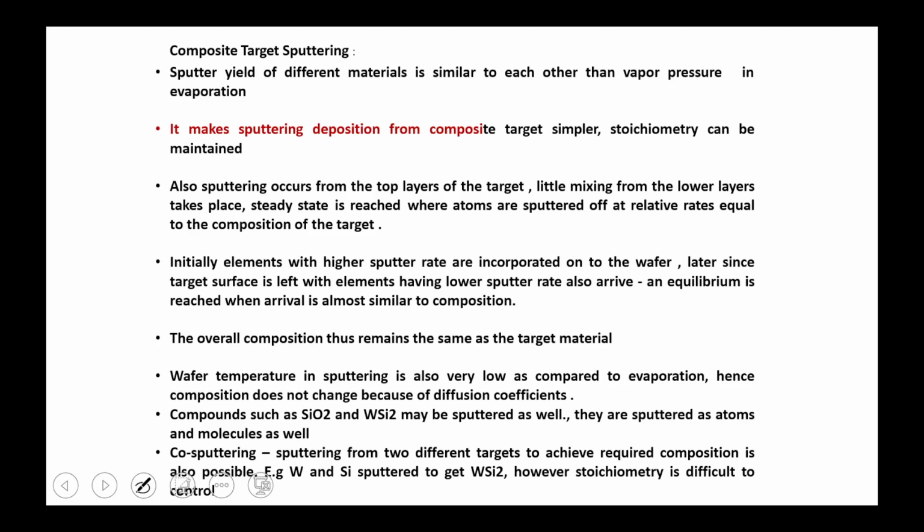The top layer thickness should be less, so that it will be striking the bottom layer's atoms also with higher energy. Some bottom layer atoms should also evaporate from the target, and then the composite will be deposited on that substrate. Otherwise, it will be difficult to pull out the bottom layer atoms parallelly with that RF plasma surface.